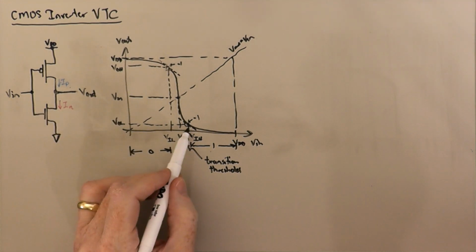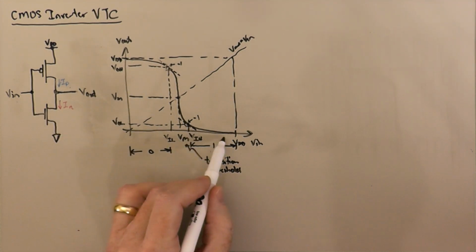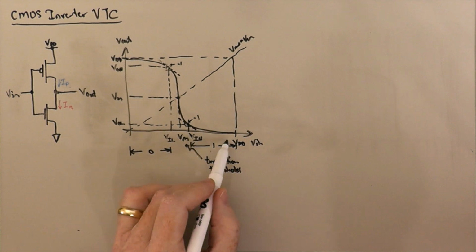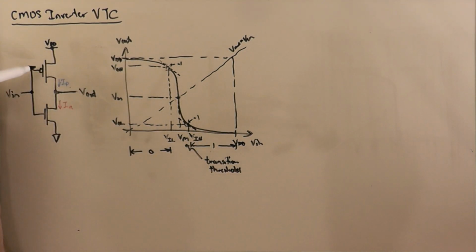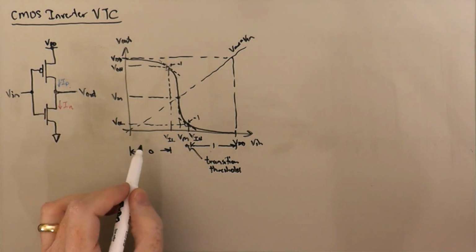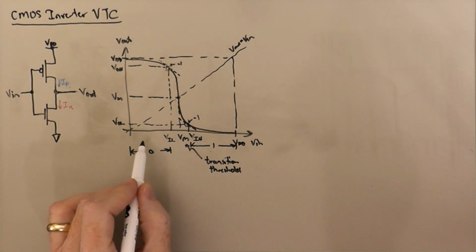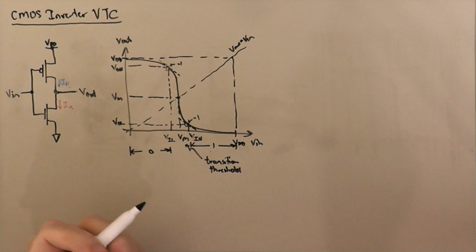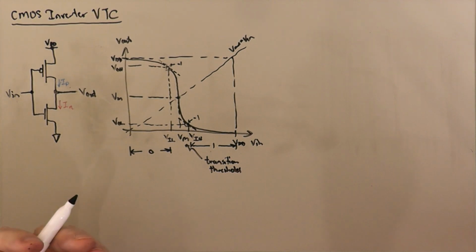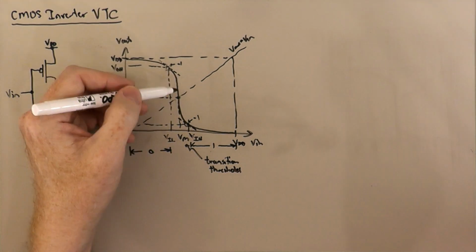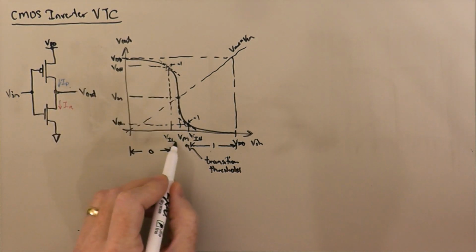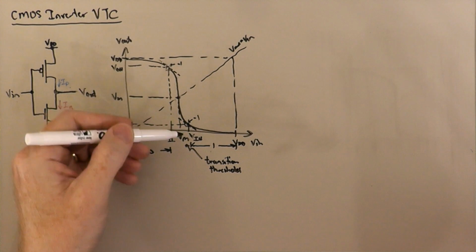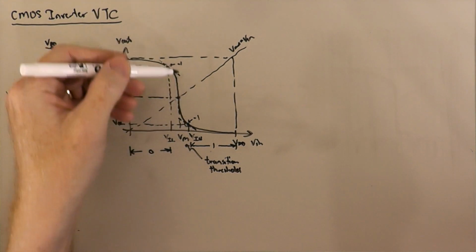So in this region that I've labeled 0 and 1, the inverter attenuates those variations in the signal, so it basically attenuates what would be considered noise. Whereas here in the middle, this is steep, and so if I wiggle around in here, my output is going to bang around by quite a lot.